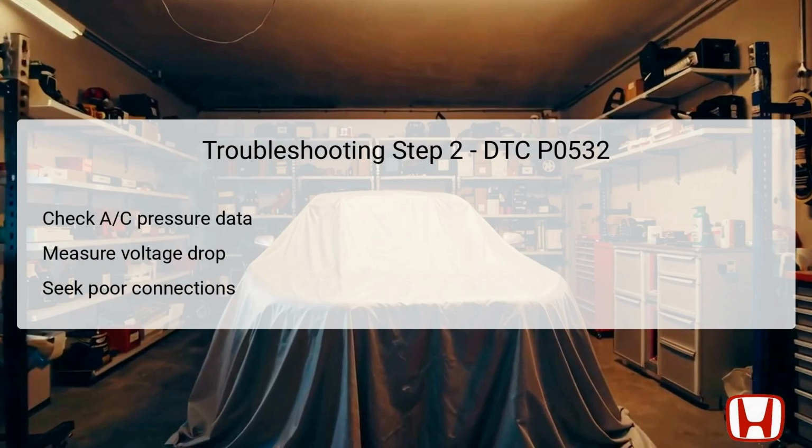In the second step, the goal is to assess the data captured during the first step. Once the AC switch is engaged and readings are obtained, verify if the AC pressure sensor shows a voltage of approximately 0.24 volts or less. If this condition is present, it signals a possible fault in the sensor or circuit, prompting the technician to proceed to the next steps in the diagnostics. Alternatively, if the voltages fall within normal ranges, consider this as an intermittent failure.